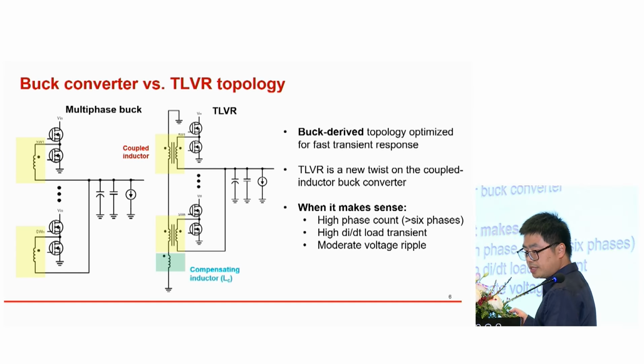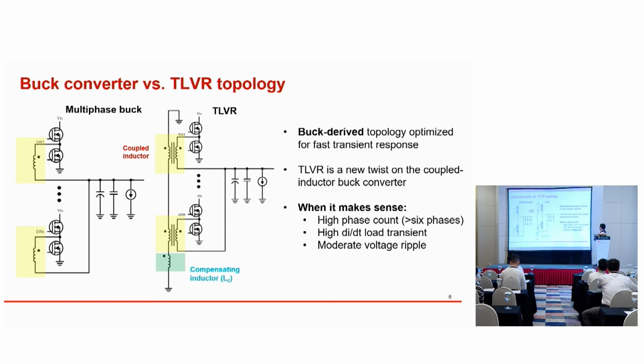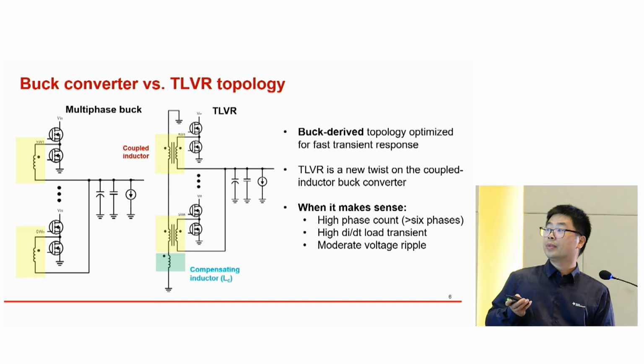When does it make sense to use the TLVR? I recommend it when you use a higher phase count, larger than six phases. But if you use a low phase count, it is also possible.